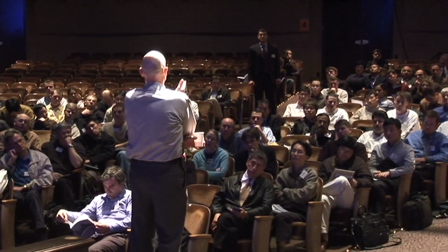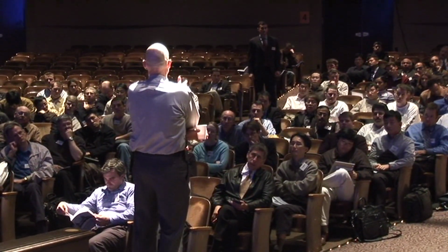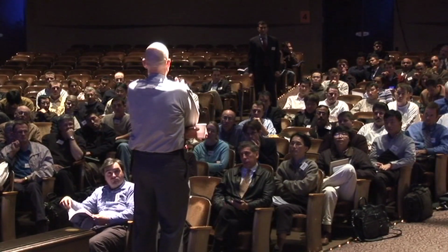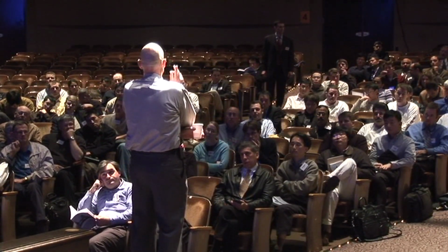I can't go into the details here, but it turns out if it's a reinforced concrete beam, it's quite easy to get the corresponding hinge rotations. In fact, they're exactly the same as the rotation capacities for a reinforced concrete beam. For a steel beam, that's not the case because it's defined differently. But for a concrete beam or column, you can put in a plastic hinge or a PMM hinge, and basically you use the same rotation capacities that you would use for a FEMA beam.